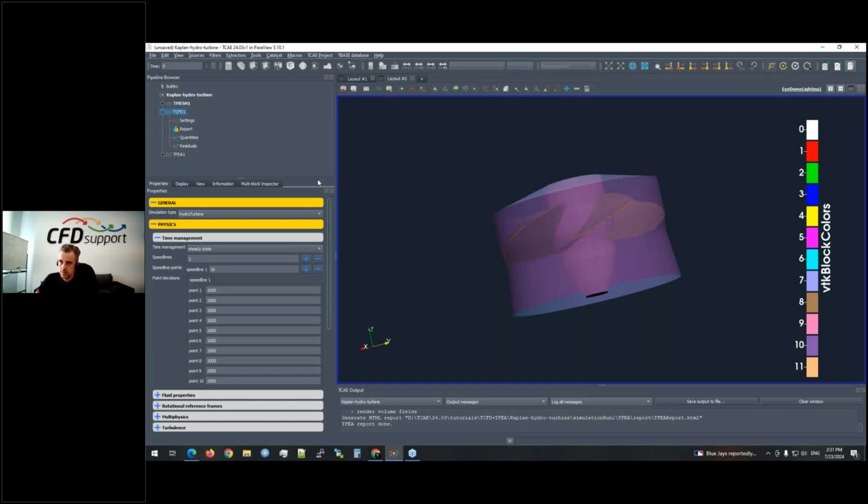But for every simulation, you have to decide something we call time management, which means how, or at least what, I'm going to simulate. The first critical decision is steady state versus transient. Steady state simulations are quick and fast enough to see a lot of simulation points, and transient simulations are more comprehensive in accuracy, and they're important for special physics.